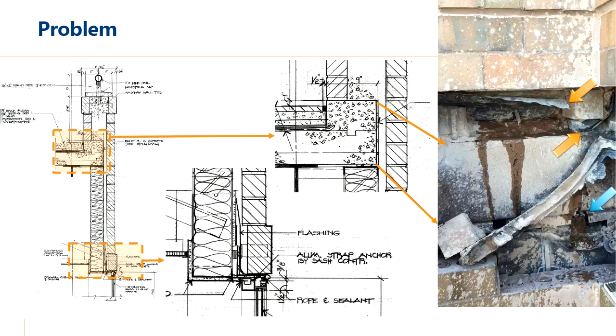We also had a number of penetrations with all those steel rebars that went through that. But what's happening is that water was coming down, rolling down the face of the structural edge of the slab. And when we got to the sheathing down below, there was no coordination regarding the top of that. And water was just rolling into that bent steel plate and dropping in behind the wall. So there were issues down below at the headers that they had replaced, and we had issues up at the floor level.